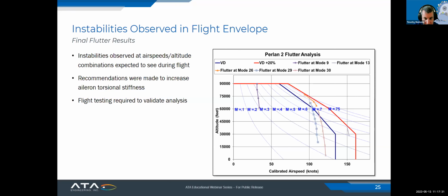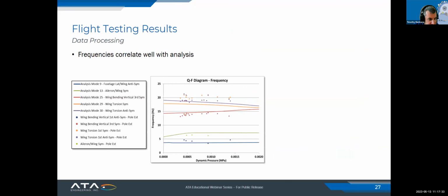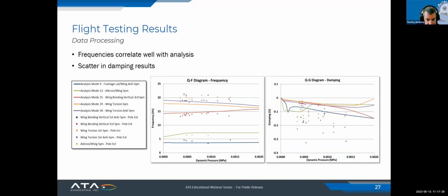Let me go back to the data, mode 9, so that's blue. You really don't start to see it as you get higher and the damping goes way down. So basically, it was almost no longer being excited at that higher altitude. Did I answer your question, or did I just talk around it? Oh no, that's fine. Okay.